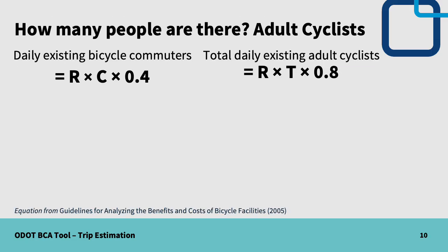Determining how many people to include starts by calculating the number of residents within an area and applying factors to narrow down this number to a realistic estimate of people who would walk or bike along the new active transportation infrastructure. This can be done by looking at census data for population, journey to work mode used, and the percentage of the population that are workers over the age of 16, potential commuters, or the population over 18, potential adult pedestrians or bicyclists. Using these sources, follow the equations on the slide as found in the NCHRP report.